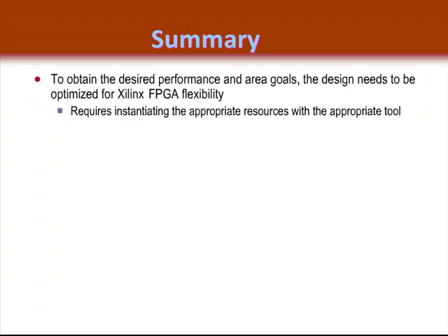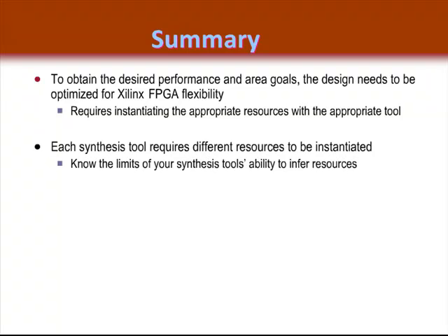In summary, your ASIC design is going to need some optimization to whichever FPGA you choose. The problem is that today's FPGAs have so much dedicated hardware logic that synthesis tools just cannot support inference for all of their functionality. In fact, one of your challenges will be to instantiate the resources you need for your design. To aid in optimizing your design, Xilinx provides the Architecture Wizard and the Core Generator utilities to speed up your design conversion.